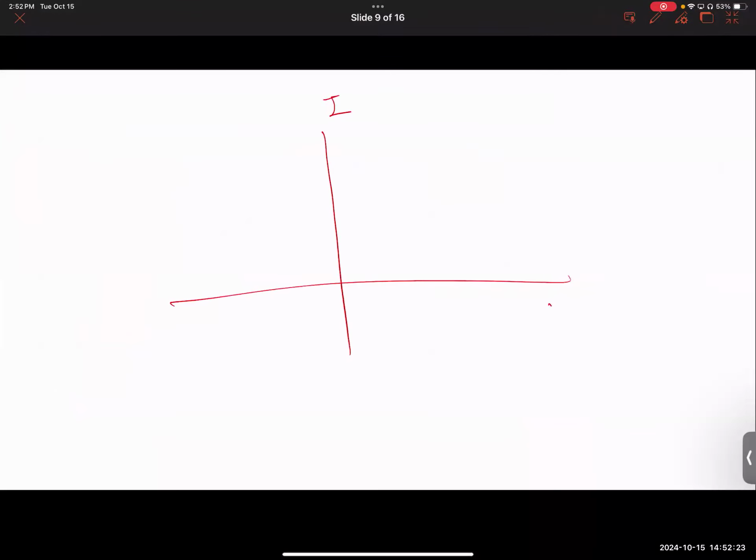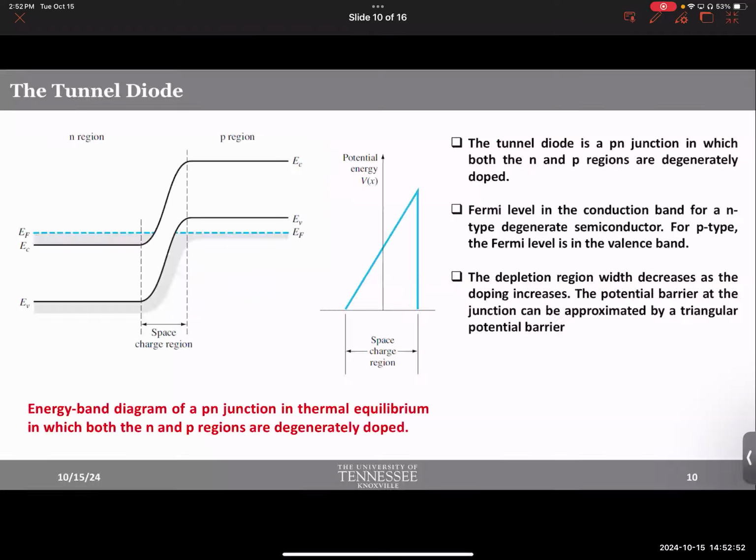So current versus voltage property, forward biased situation: there is a diode drop or turn on voltage beyond which the diode starts providing you current in an exponential way. And in the reverse bias sense, there is almost no current, almost negligible, until a certain point when there is a breakdown, and then you have a really, really abrupt switching current. Okay. Very simplistic overview of a diode IV property.